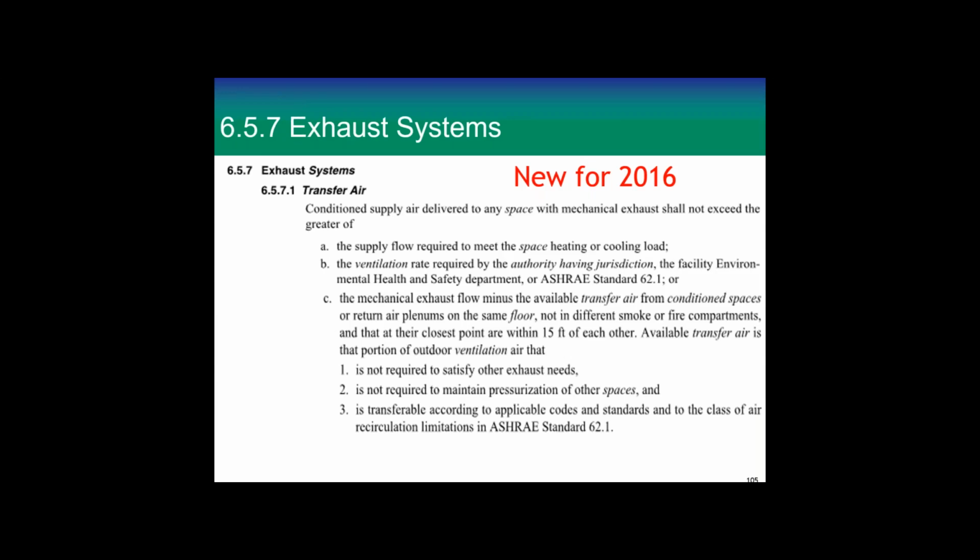Exhaust systems, new for 2016, is transfer air. So we've always had requirements for kitchens that you make up the hoods using transfer air. So this is an extension of that. What we don't want you to do is to put air into a space, suppose it's an equipment space or a restroom, that is directly going to immediately exhaust the air we put in there. So it's much better to reuse the air from another space.